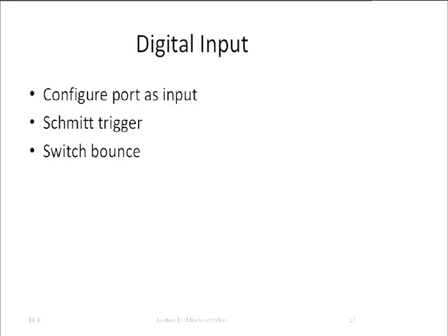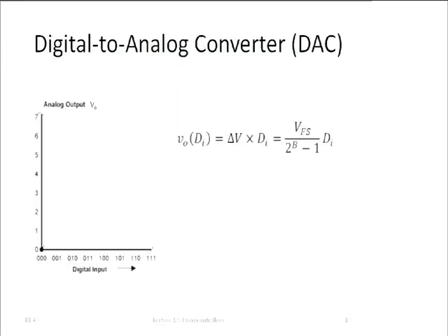All right, so now more interesting, analog input and output, also something that we talked about a little bit informally, or we looked at the circuit. Now, what does it really do? Well, here first a digital to analog converter. So what's the input? The input is a binary number, and in this simple example, it's a binary number that has 3 bits. So it can go from 0, 0, 0 to 1, 1, 1, and anything in between, signifying the decimal numbers 0 all the way up to 7, right?